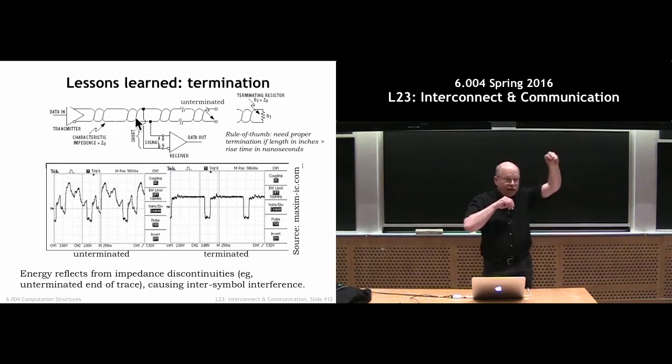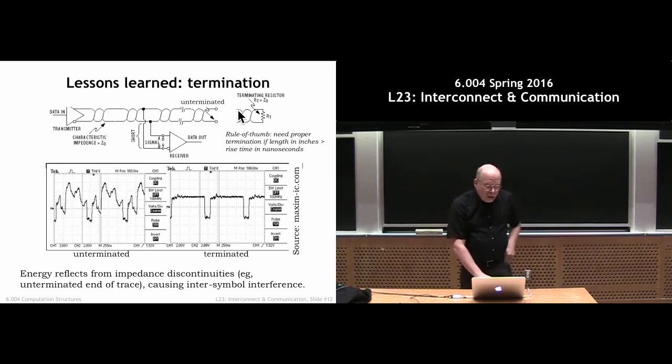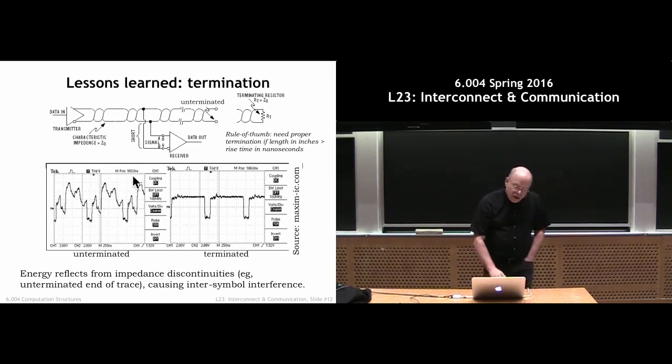We're basically putting a positive signal on one wire and a negative signal on the other. A way to think about this is we're measuring the difference between the two wires to get the signal. That's what differential signaling is all about. Look at the difference between the two wires, which turns out to be very reliable against certain types of common mode noise. Maybe that makes sense. Maybe it doesn't really matter.